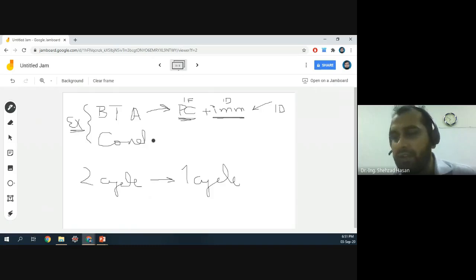But what about condition evaluation? A condition evaluation needs the register contents, and we read the register contents in the decode stage. So for condition evaluation, we need the register contents, and there are always going to be some simple operations between registers. So let's say we have an operation between R1 and R2. That could be a simple comparison operation, or a sign checking operation, whatever. But we have to do some operations between registers.